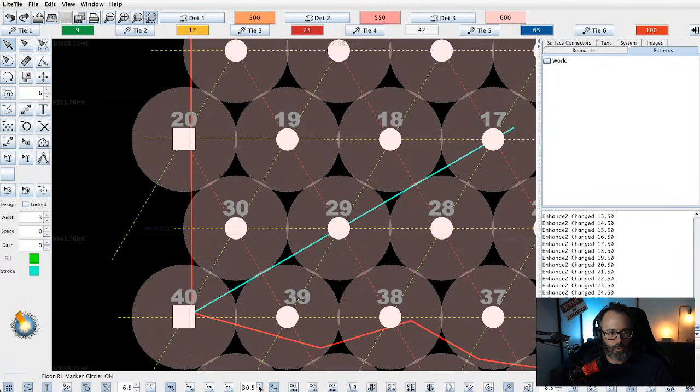So this is sort of like where our blast is overlapped to, and we want to move our blast hole number 40 in, but we want to maintain this circle out here because that's where the blast hole should be, and we're expecting that there's some toe and stuff around here, or the angle of the face is down there. So we're really targeting the toe of the hole at this point. So for starters, let's select hole 40.